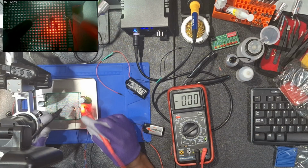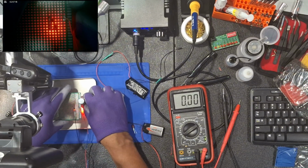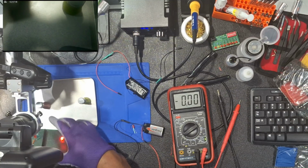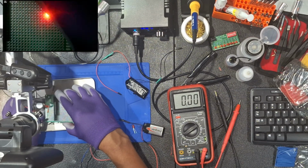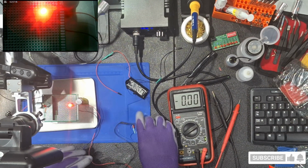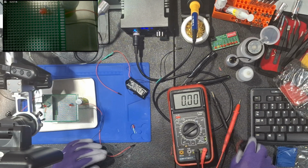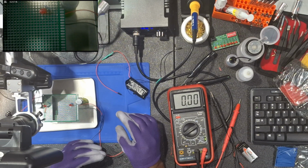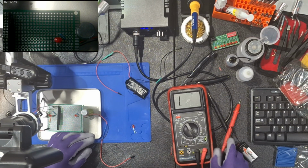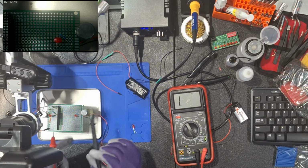And it's based on the value of the resistor, which determines how much voltage and current it will restrict. This is where the value of the resistor comes into play, because the value determines how much current will be restricted. So if I had used a higher value resistor, it would resist more current, so the LED would have been dimmer. With a lower value, the LED would have been much brighter. Also, a lower value can result in the LED burning up. If the value is too low, too much current will go through, more than what the LED can handle, and that's what causes it to burn.